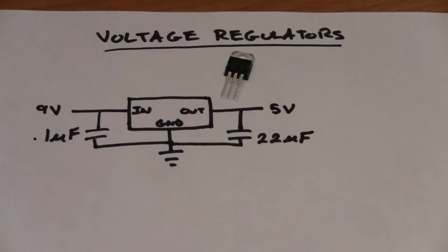The last thing we're going to talk about today is voltage regulators. We just talked about a voltage divider as a great way to get a lower voltage out of your circuit that's providing a higher input voltage. But if you want to use something that draws a fair amount of current and is using a fixed voltage, then a voltage regulator is the way to go. The reason being is that voltage dividers will give out above a certain output current and will start to fall off in performance and the voltage that they can provide, whereas voltage regulators up to a certain current are guaranteed to always output that voltage despite the input current, as long as it's above a certain value.